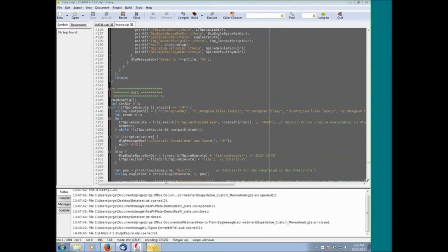It will also do S-parameter simulations, and on top of that, it can do SPICE simulations. So the one next month is actually a pretty heavy-duty program, and its interface with EAGLE is different than the one LTSpice has with EAGLE. We'll check that out next month, and I'm sure you guys will find it very interesting.